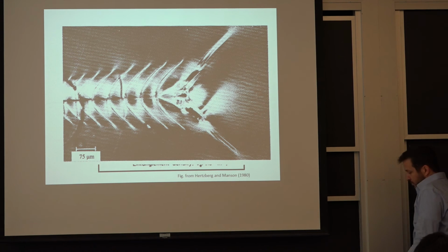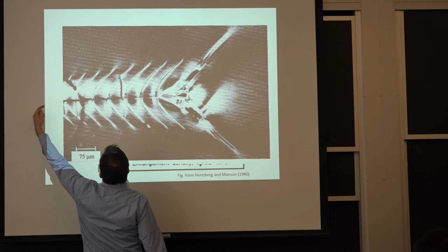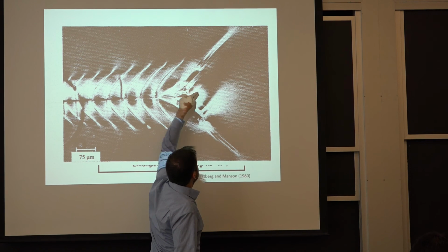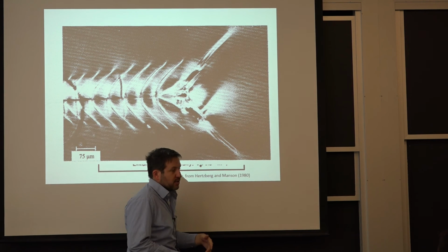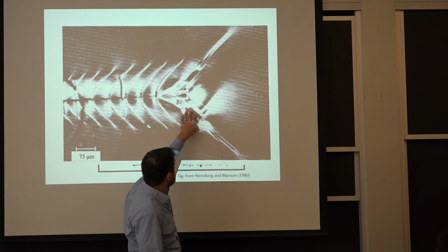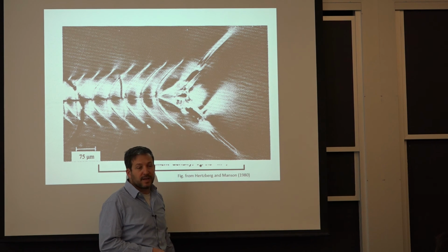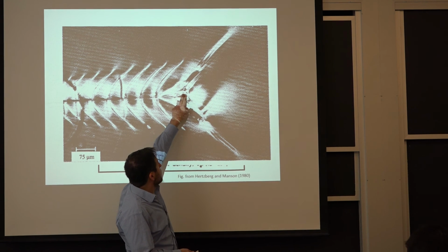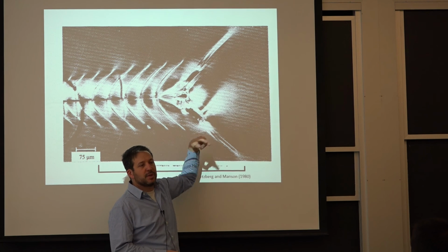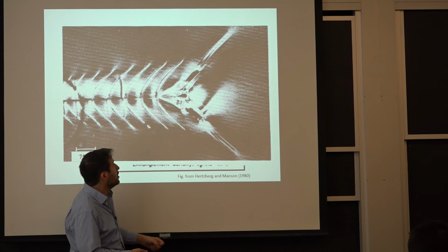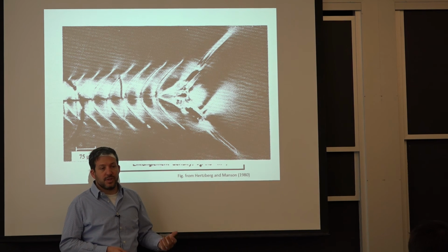The crack is propagating this way. So when it's at this slant, right here, you have a lot of shear on each side that is stopping the crack. And that's why polycarbonate is just very, very tough to the growth of cracks, because it's absorbing a lot of energy at the crack tip through this shear banding process. Now, if we're here, eventually we'll move up. When we consume all the energy, especially if it's a cyclic load or if there's just plenty of power to keep opening the crack, it's going to continue to grow.